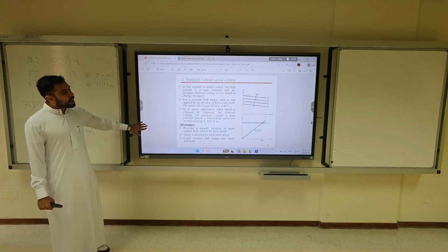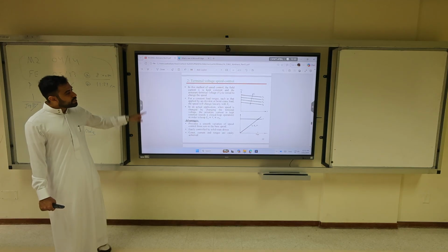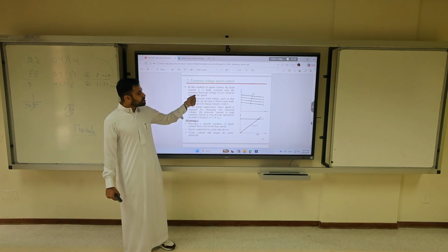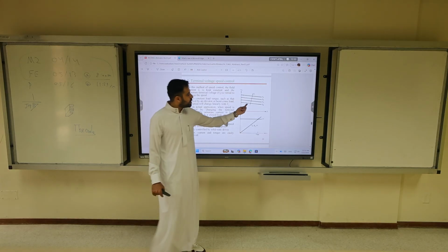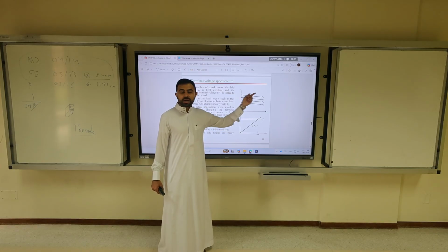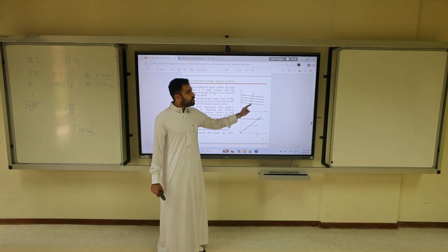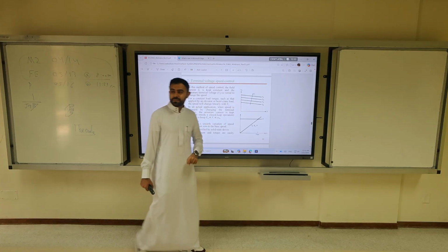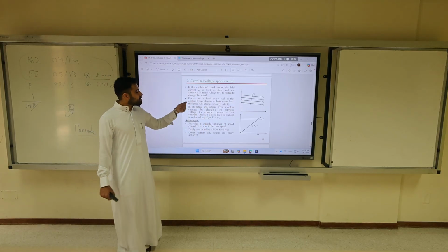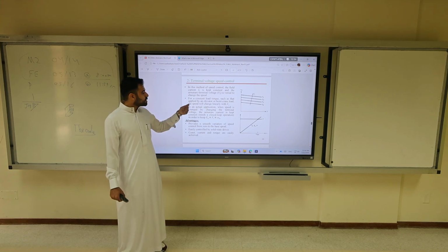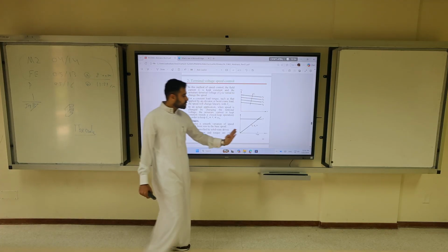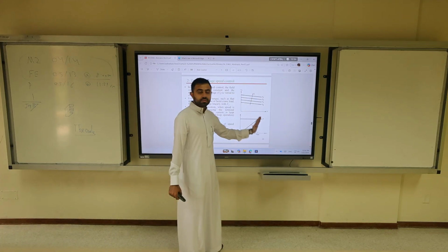Terminal voltage. What will happen with the terminal voltage? In this method of speed control, the field current is kept constant. Armature voltage is varied. So if you increase the voltage, what will happen to the speed? Increase. So always look at these figures. If you increase the voltage, what will happen? It will increase. For a constant load torque, such as an elevator hoist, if you have a constant torque load, it means your torque is fixed, constant.